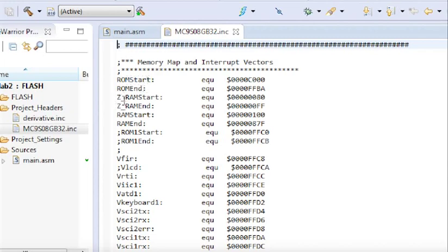And then we see ZRAM start, which is zero-based RAM start, so we can see that RAM starts at 80 and goes to 87F. So we have this kind of information available in the assembly portion, but not in the C portion. That's why we're sort of poking around here. So let's take a look and see how we can start writing up part of the lab.